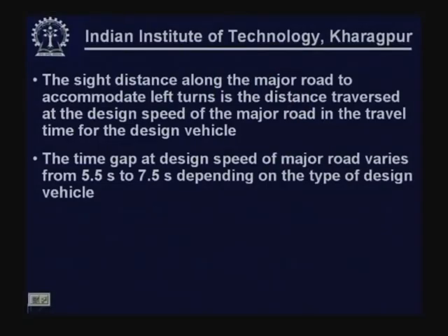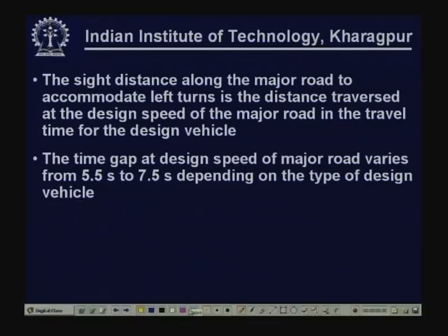along the major road. So, this time gap as per AASHTO is 5.5 seconds to 7.5 seconds. That is the time gap which is recommended by AASHTO based on field observations. And this value, 5.5 seconds to 7.5 seconds, varies depending on the type of design vehicle.